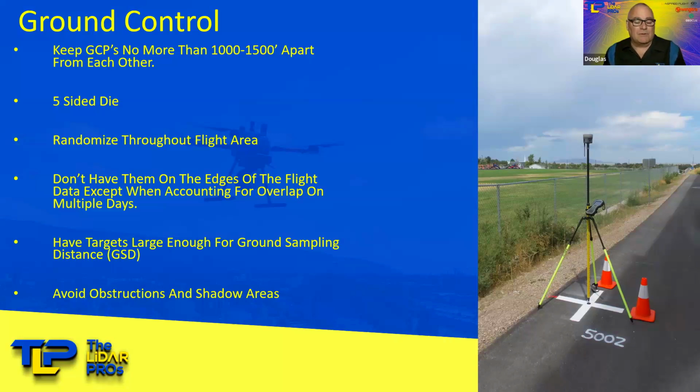And this allows us to, instead of visually tying that point to where the drone is in the sky, take the data from the base station and put that into Pix4D or whatever other tool we're using to precisely pinpoint where that image in the sky is located down on the ground. And this will tie us together.